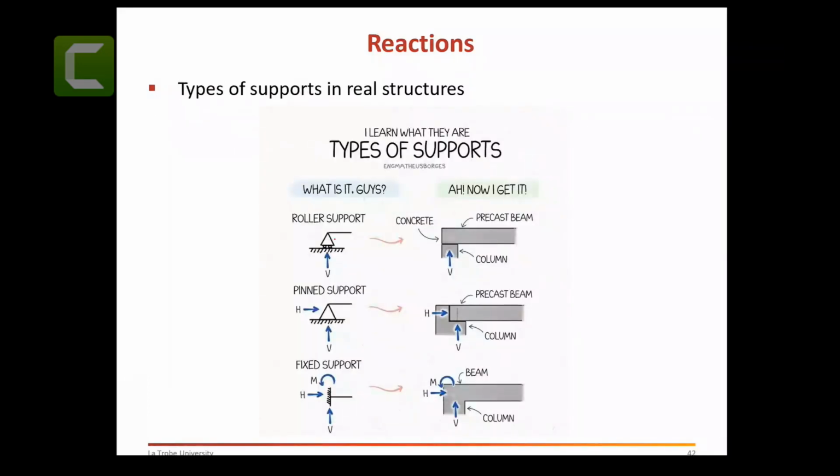Okay, you look at here that you can see the roller supports. How do roller supports work? You have seen the columns and you have seen the beam. In real situations, you will not see actual rollers. You need to make an engineering decision that this point here can go left and right.